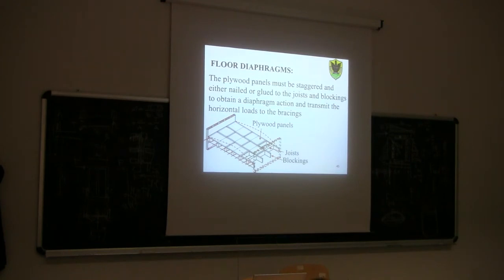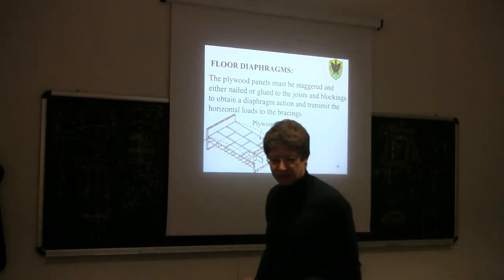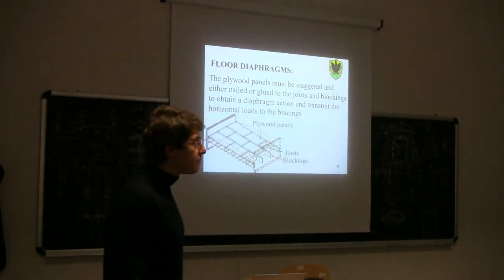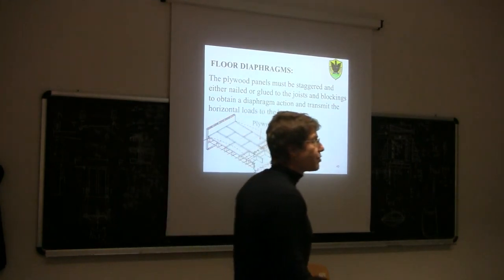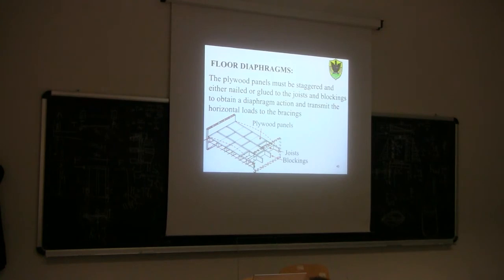So a simply supported beam subjected to a uniform distributed load is loaded with what kind of internal forces? So shear and bending, but shear in plane or out of plane in this case? In plane, so in-plane shear and bending, in-plane bending, okay?